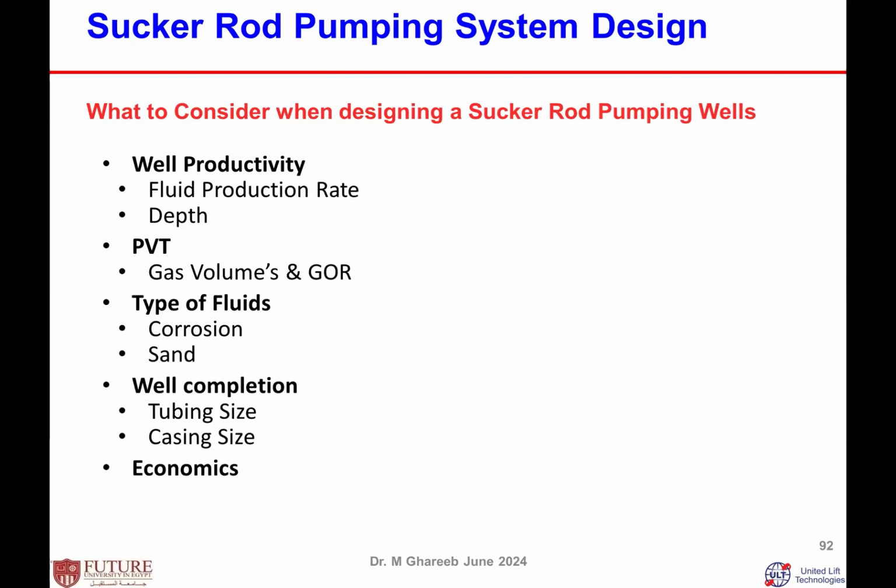Like all the other types of artificial lift, when I need to design the system, I must put in front of me all the possible information, like the well productivity: how much fluid will be produced from this well at a certain bottom hole flowing pressure, and what the pressure at the pump intake will be, in order to allow me to design the suitable depth to run the pump.